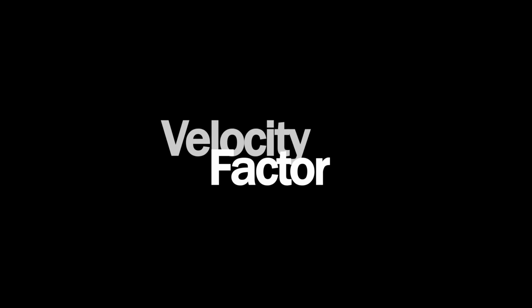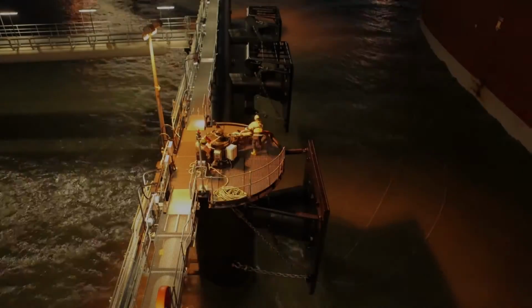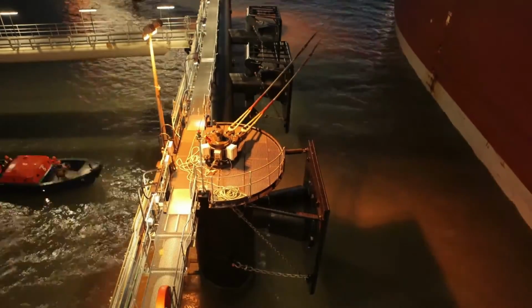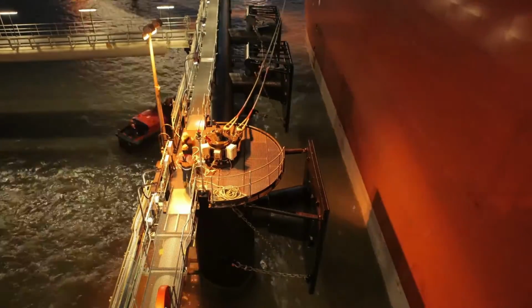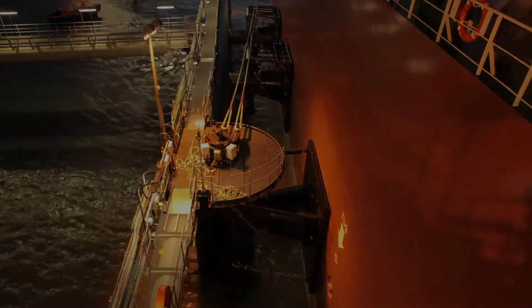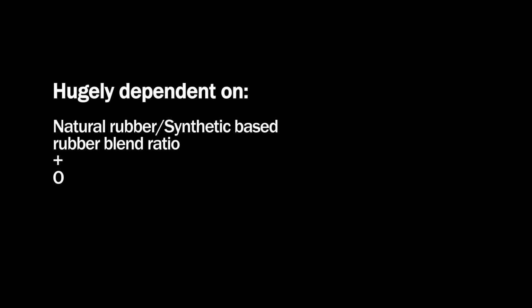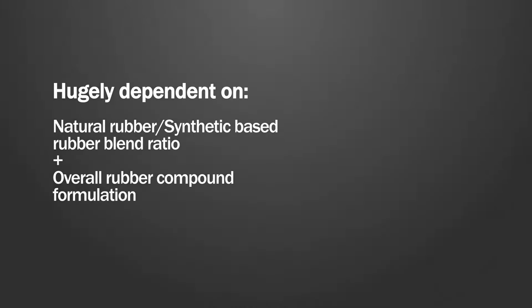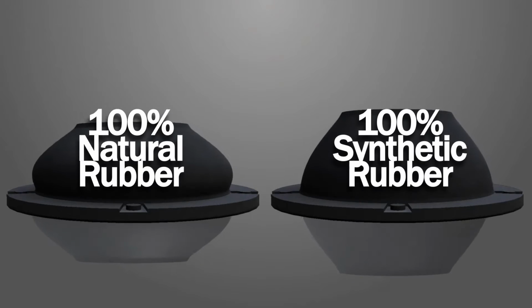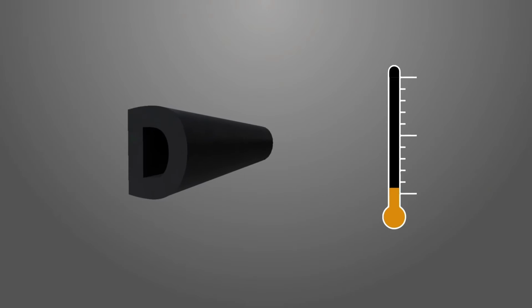Fenders should be tested at realistic berthing velocities to determine actual performance, but it's difficult to test at the speeds fenders will be subjected to in the field. The correct application of velocity factor is highly dependent on the natural rubber to synthetic-based rubber blend ratio and the overall rubber compound formulation. Given the same compression time, a fender comprised of 100% natural rubber will have a lower velocity effect than one composed of 100% synthetic-based rubber.